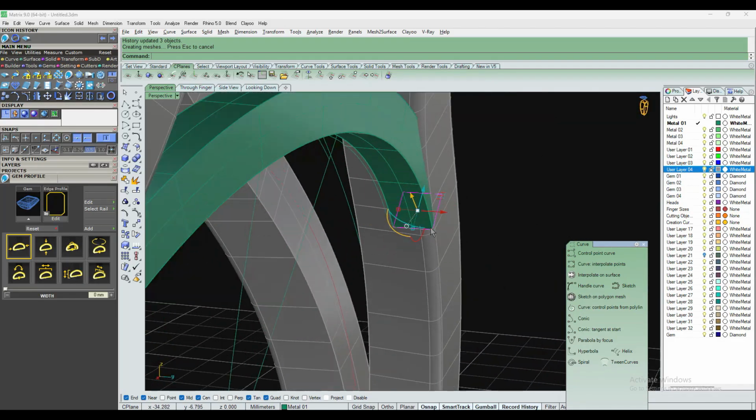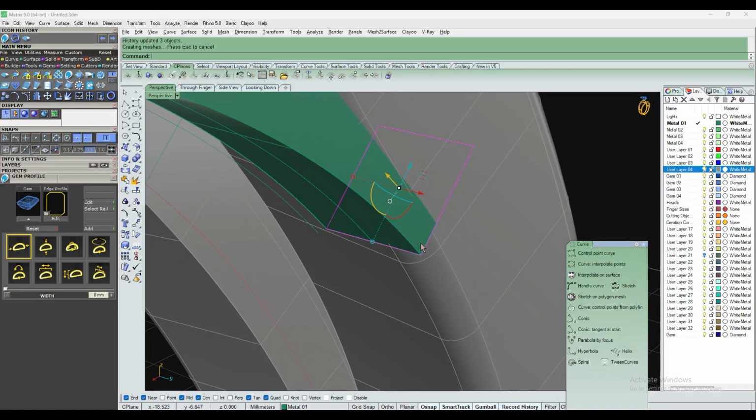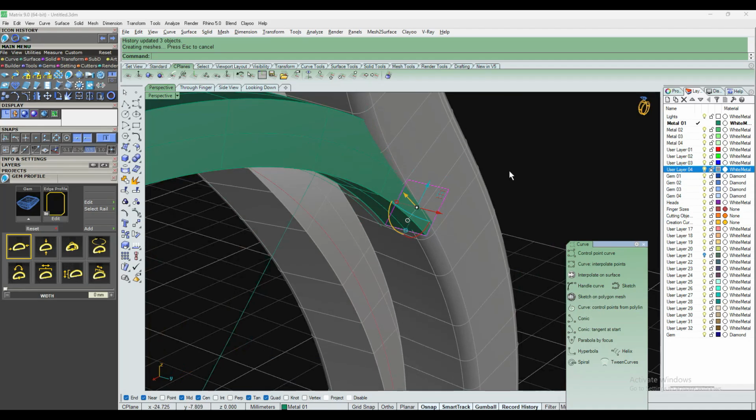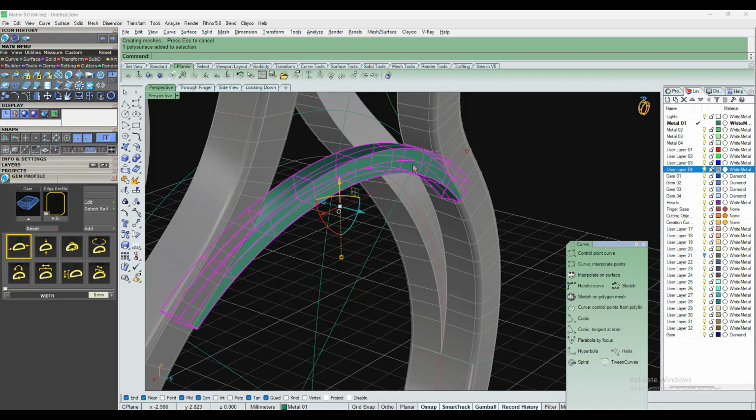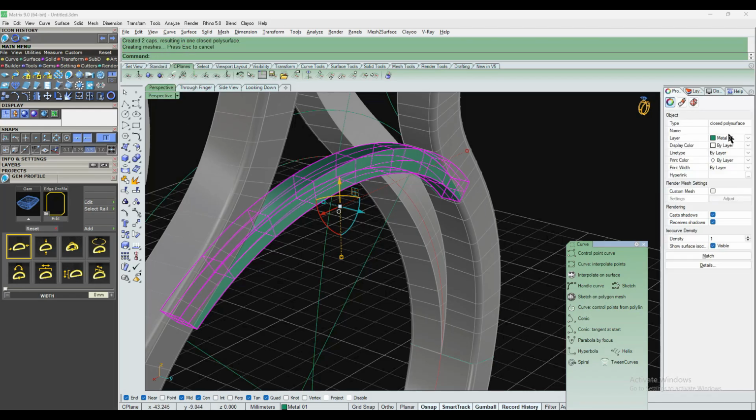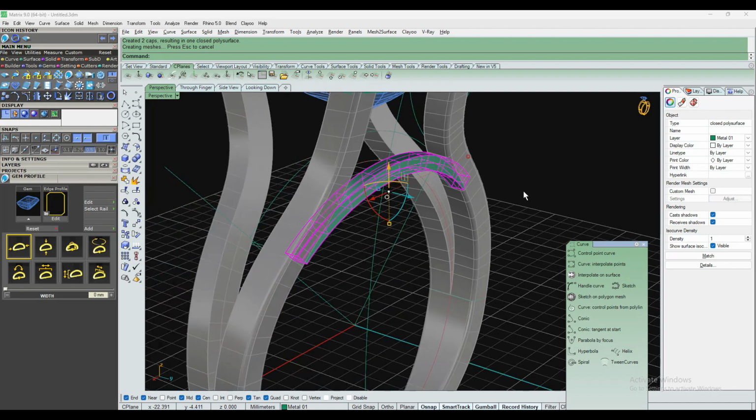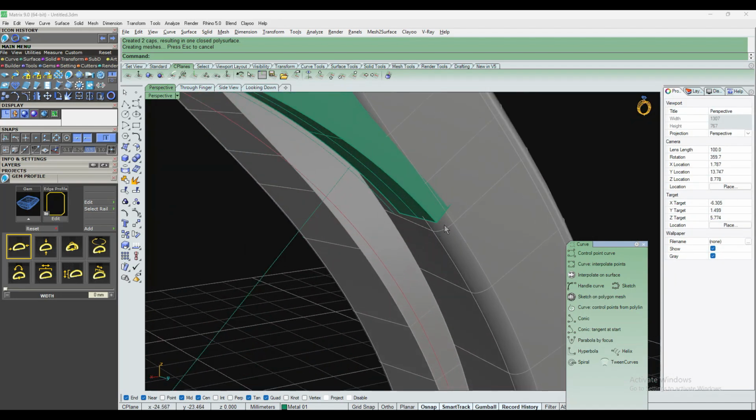Okay, you need here a 0.2 mm radius. So for now, select this object, type in the cap command. So cap will convert this object into a solid. You can check here using the properties. Okay, so now this is a 3D solid object. I cannot use this fillet.